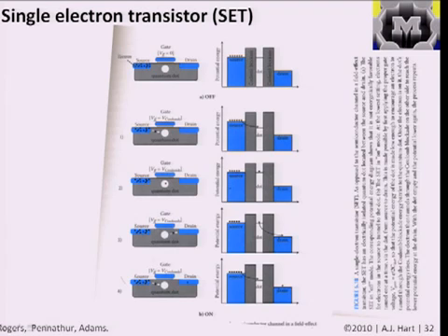And so I've described already what basically is happening down here, but down in the bottom pictures we see physically a diagram of the transfer process. So when a voltage is applied to basically overcome what's called the Coulomb blockade in the device, you reduce the energy structure of the quantum dot and basically create a space for an electron to tunnel across an applied voltage difference between the source and the drain. And then you store one electron on the dot, and then the electron tunnels across onto the drain, and then the same process can repeat itself again over and over.